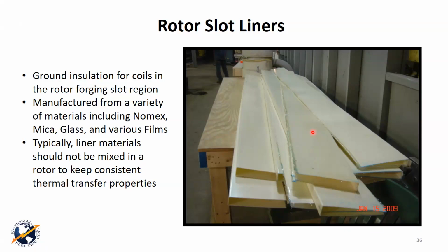But when you do that, you need to make sure you still have enough material left, and you have to do an analysis to make sure you still have a mechanically reliable forging. Anyway, that's the slot liners, and hopefully that helps you a little bit, Ken, on the boresonic inspection. And it is using a bore scope, but they traditionally call that inspection technique a boresonic test of the rotor.